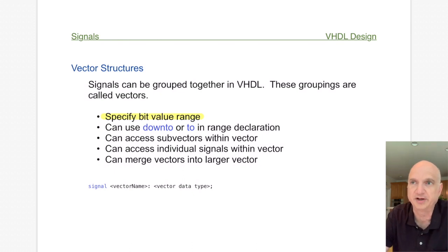So if you look at a binary byte and talk about bit 2, you would start on the right-hand side, that'd be bit 0, then bit 1, and then bit 2. So you're looking at the bits in the order in which they are from right to left. And that's kind of how we can do things inside VHDL. When we declare a vector, we can give numbers to the individual signals inside that vector.